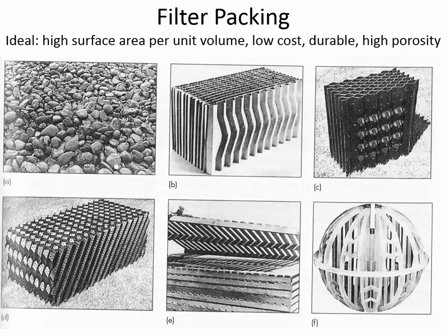What they're going for in these proprietary filter packing systems is just trying to increase the surface area, because the slime grows on the surface of the media, and so the inside of the rock isn't doing any good.